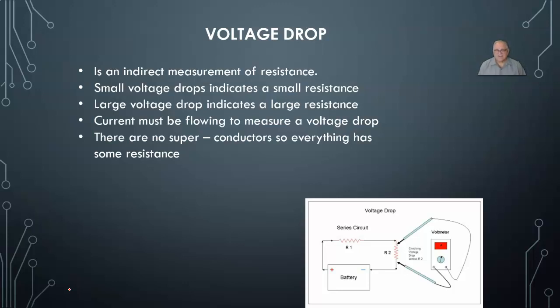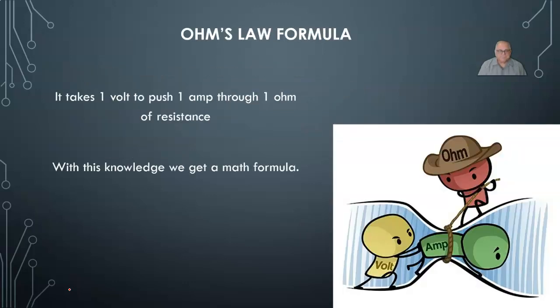If you exceed that, there's something wrong with that wire. A loose connection, corrosion, something on there, and it needs to be fixed. So we don't need to know exactly how many ohms. All we need to know is that, hey, there's too many ohms or too much resistance, and that's where our problem is. We need to fix that.